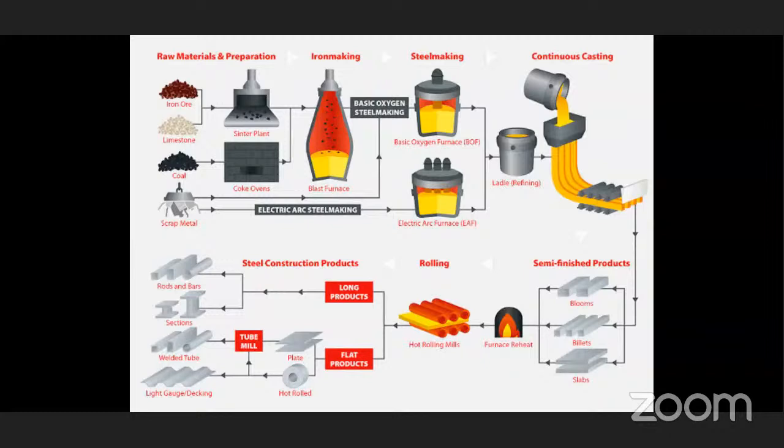In the same way, if impurities like sulfur and phosphorus are to be removed, the furnace lining that will be in contact with the slag uses refractory materials such as dolomite and magnesite. If you use acid refractory materials, that is called acid steel making, whereas if you use basic refractory materials like dolomite or magnesite, that is the basic process.